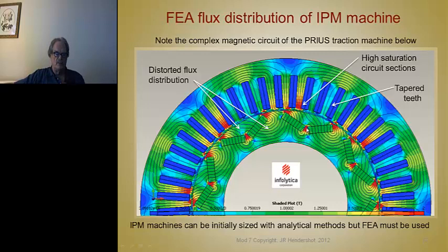Now we have another thing going on. We have these leakage paths that are inherent in the IPM machines, and those little webs of laminated steel, we don't like those there. They're there to hold this thing together. If we put air in there, then the centrifugal force on these magnets would put a very high stress on these little pieces here that hold it together, because there's nothing holding in the center. So the centrifugal force at speed on these magnets would cause this OD to expand out and rub on the ID of the stator. So the designer has put this little web of steel in there to give section modulus here to restrain the mass of this against centrifugal forces.